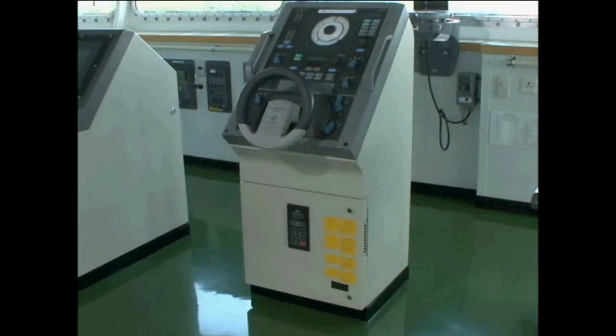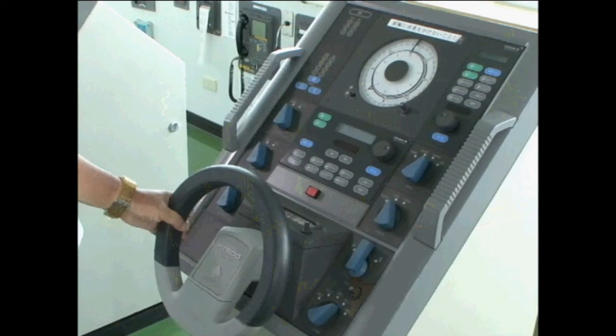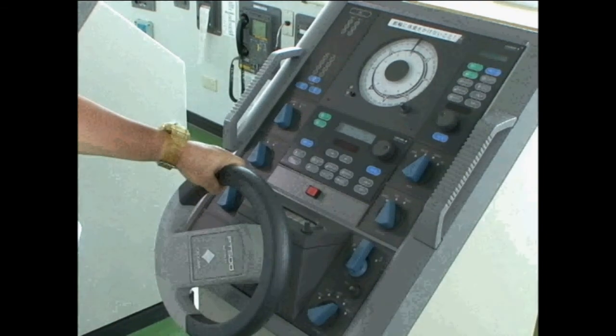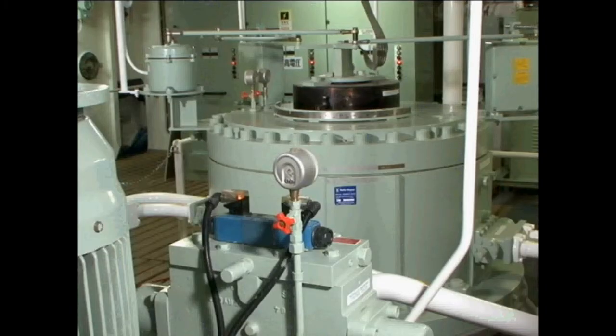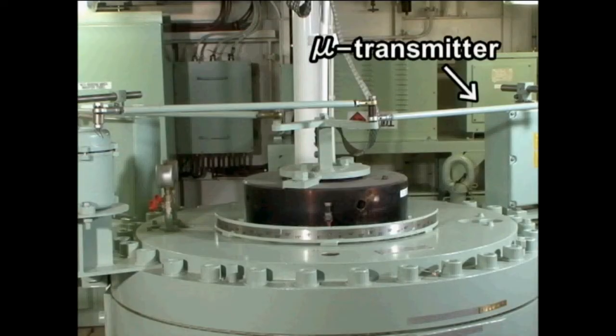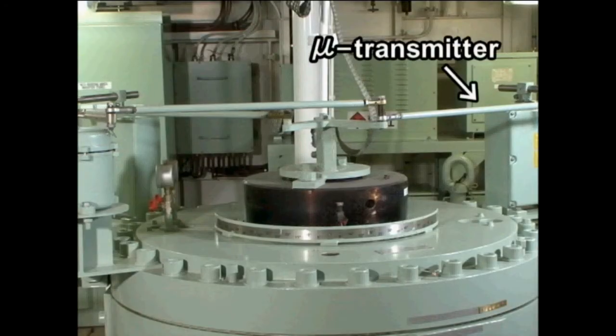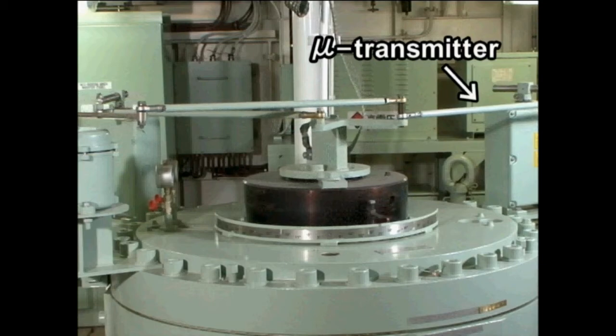The steering signal is sent from the steering stand to the control and power box as a steering control signal. It controls the piston control unit of the hydraulic steering gear using oil pressure to move the rudder. Here we'll explain a model that employs a solenoid valve as the actuator. When the rudder moves, the rudder angle signal is transmitted to the control and power box via a mu transmitter. The solenoid valve is shut when the required rudder angle signal equals the rudder output signal, enabling the rudder to hold the prescribed rudder angle.